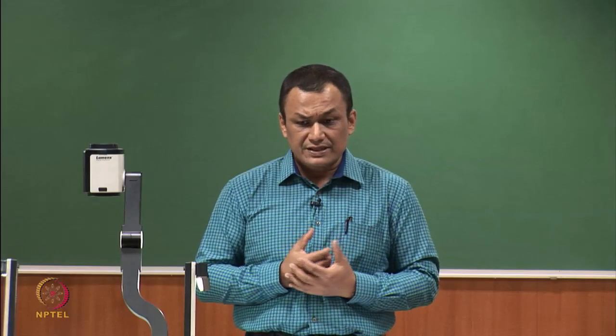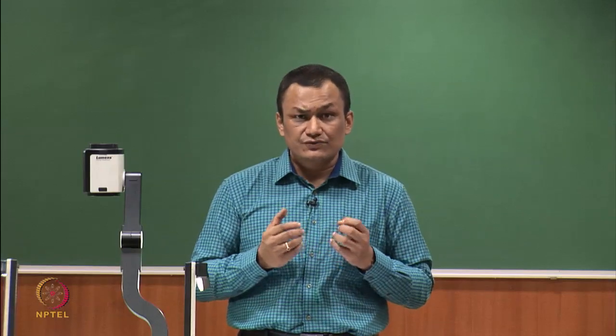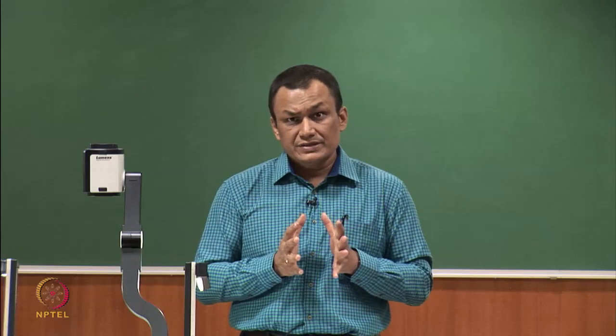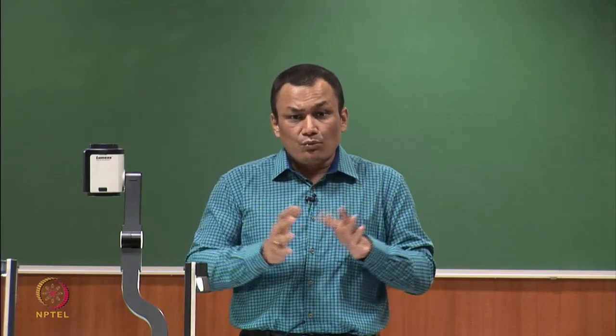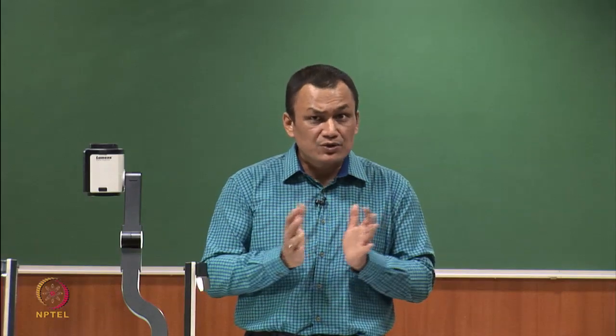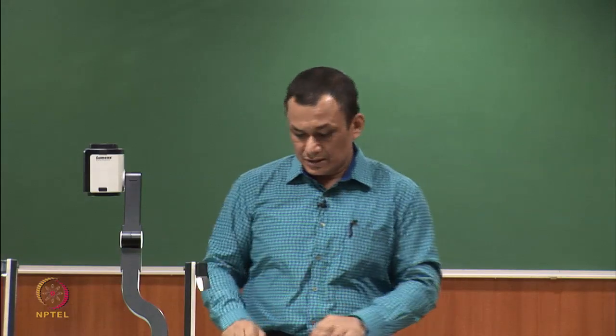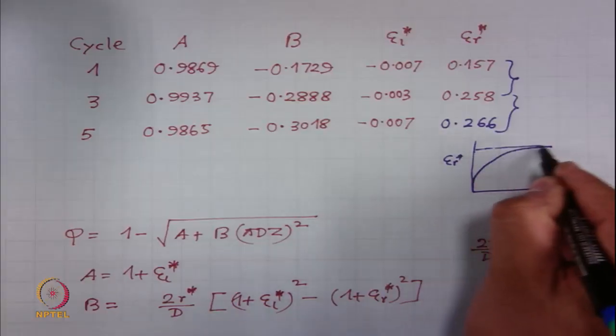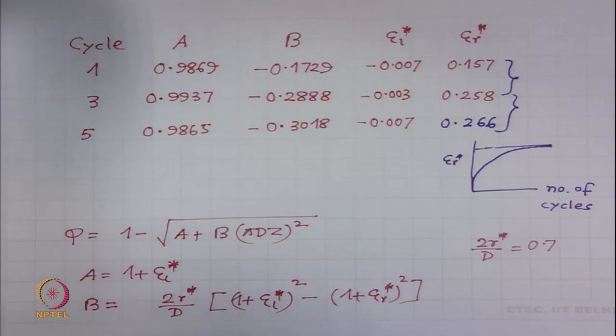Because the yarn structure initially, because of washing, swells and shrinks. So, it opens up. Once it opens up, further swelling is probably not possible. That is why this plateau comes. So, after 5 cycles of washing we did not find much significant difference in results.